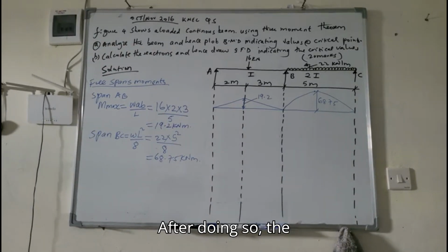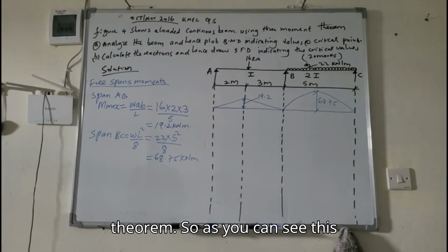After doing so, the next thing to do is to apply the Clapeyron three-moment theorem.